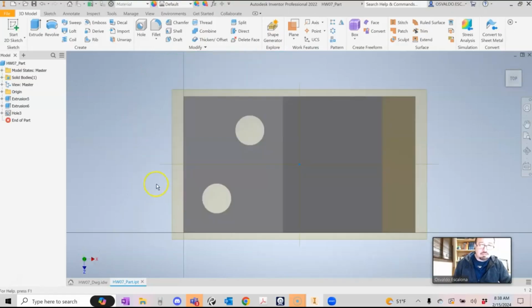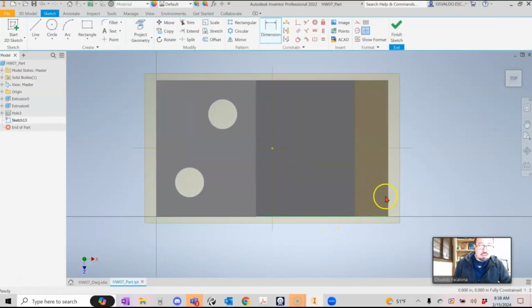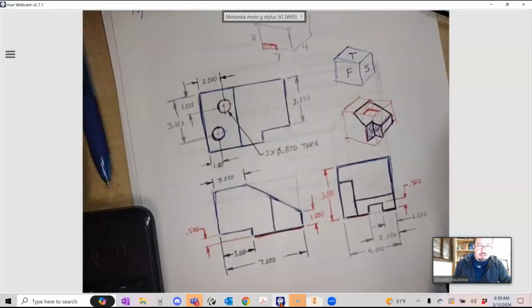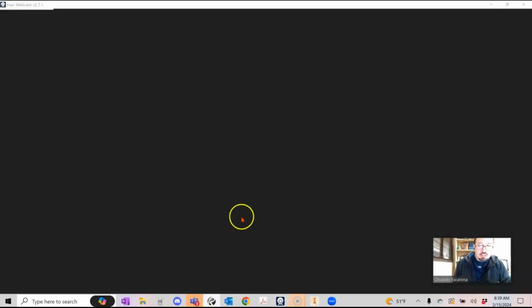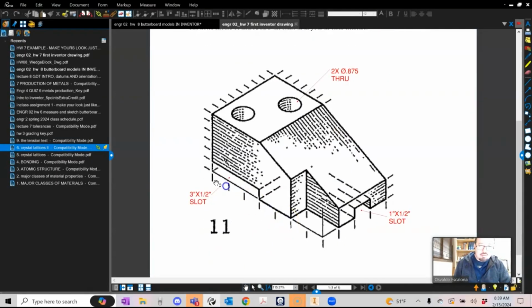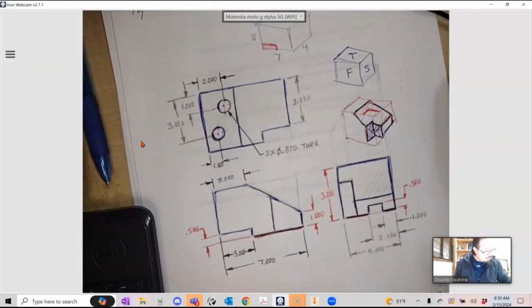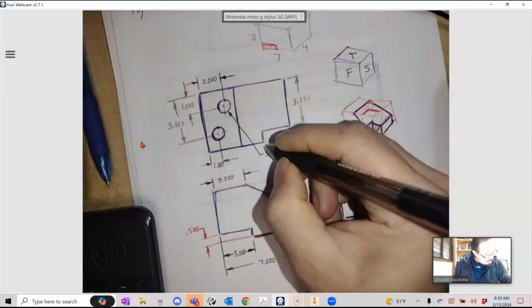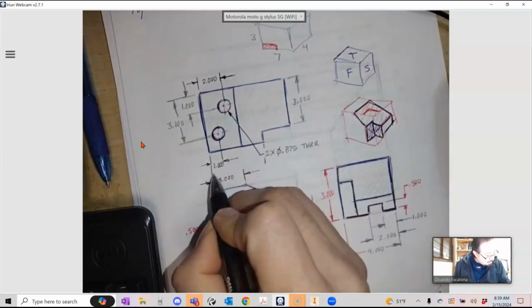So new sketch. And what I'm going to do is project a couple of lines. Project that line and that line. And then I'm going to use rectangle, so I can locate the notch that I want to do. So that one, it seems to me it is 3 and... I'm missing one dimension, guys. I need to define that guy. Let me see. I'm missing one. So this is 1, 2, 3, 4, 5. I should have checked. So this guy should be 5.